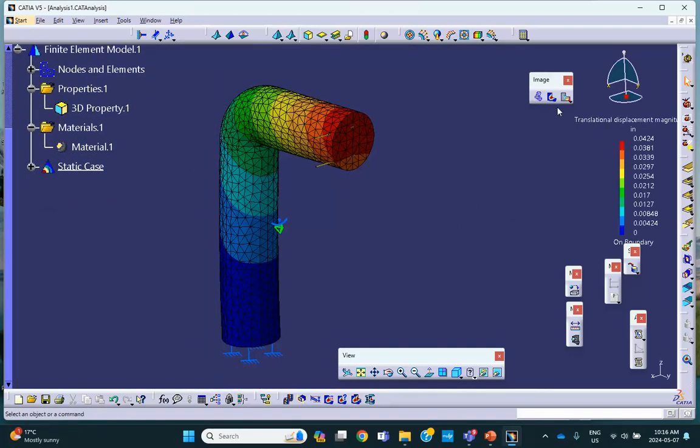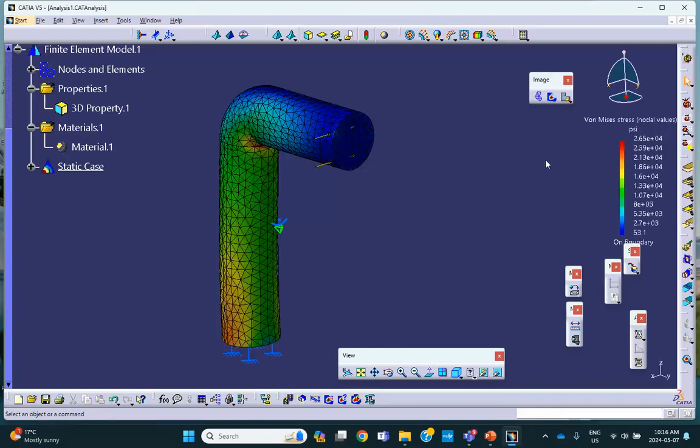Now, this is fine, except that, what about the stresses? So you click on the von Mises stress right here. You see this? Von Mises stress, you click on it. It shows you von Mises stress. Now, in the class, I forgot to change the display of the units. So it showed me in Pascal, gigantic number. But here, it shows you the biggest stresses are up here, there and there. And the magnitude of it is 26,000 psi.